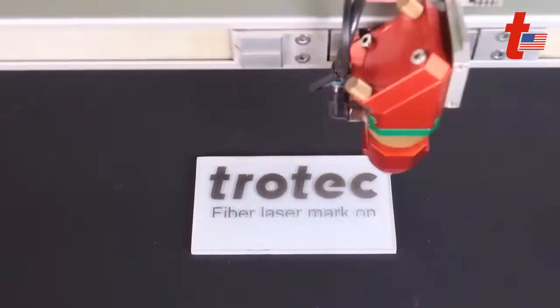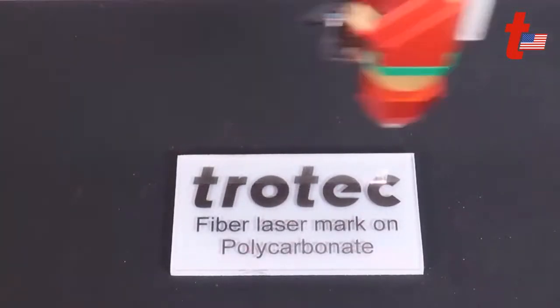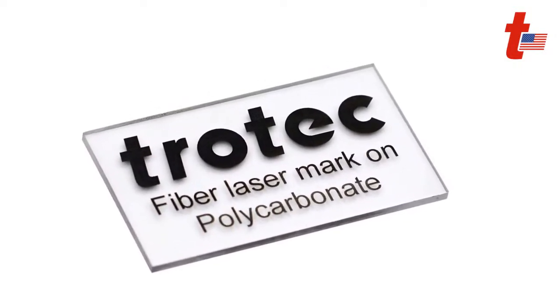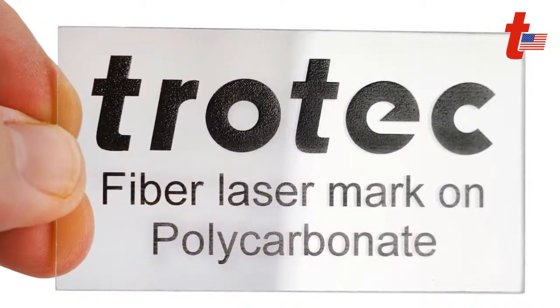So here's a good example. This is on a flatbed fiber laser. I do hit it with 2 passes typically. It will produce a darker effect, and we get a nice high contrast mark onto the surface of the plastic here. It does almost have a kind of reflectivity look to it on the flatbed system, depending on the resolution that you're running. So the fiber laser does a great job with this, and you do get that high contrast mark. It almost looks like it's been stenciled and painted, but it is far more durable and cannot be removed.